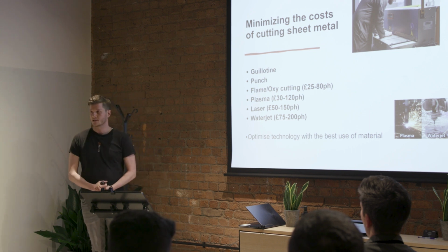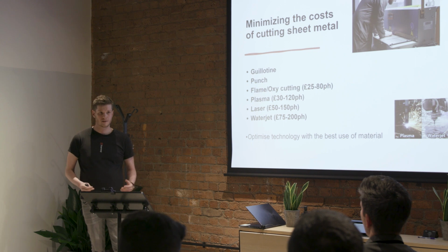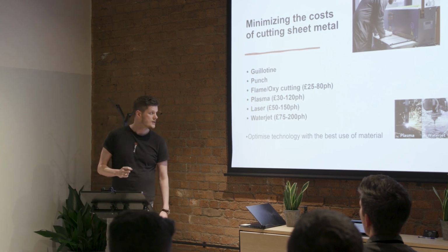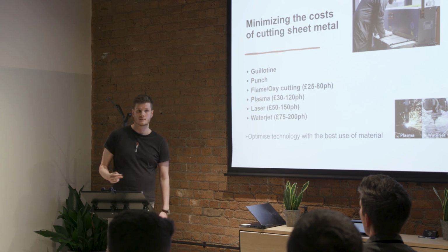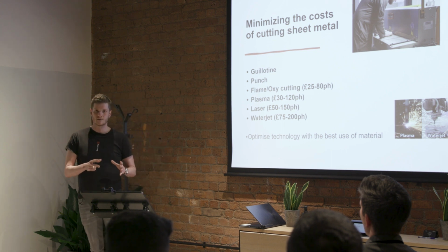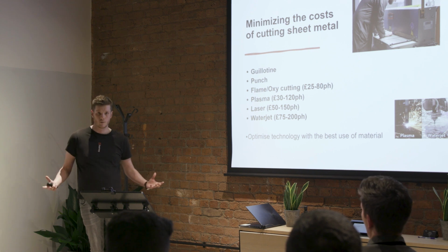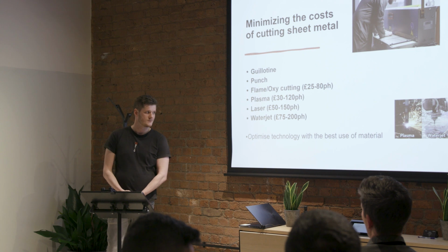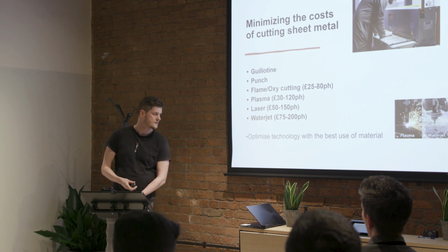With abrasives mixed in to just part the material. It gives a very, very fine cut quality finish. It has very fine tolerances, finer than laser, and because it's not thermal, you can cut smaller details into a metal part without worrying about warping, bowing, and can just create those more precise features.